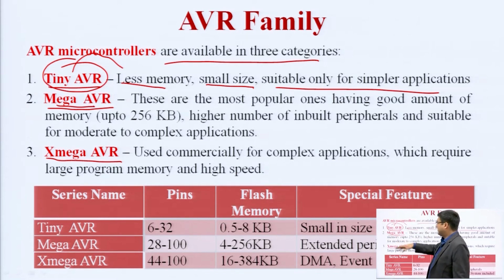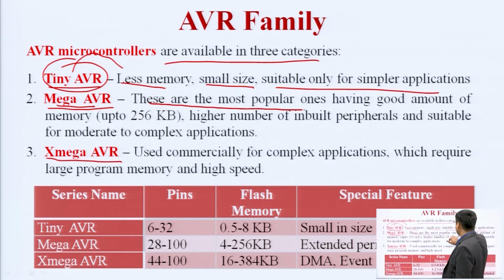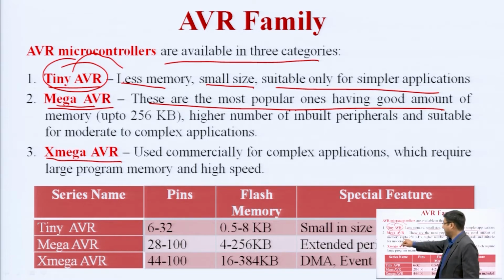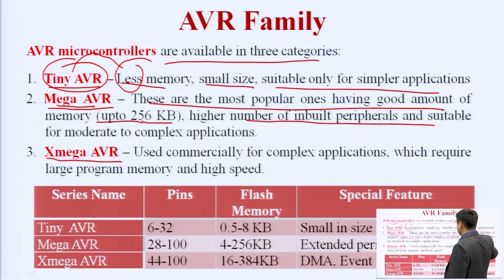Mega means something greater than its basic unit, something bigger. These are the most popular ones, having a good amount of memory. Memory is expandable. Tiny AVR has less memory, but mega has memory up to 256 kilobytes, a higher number of input peripherals, and is suitable for moderate to complex applications.